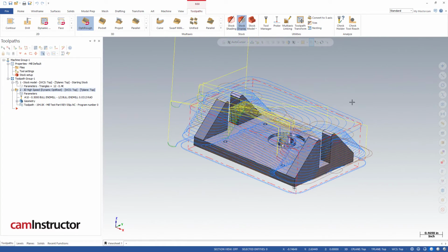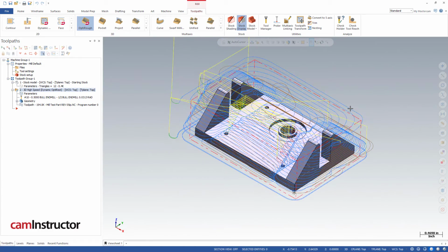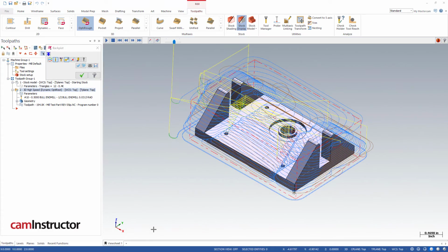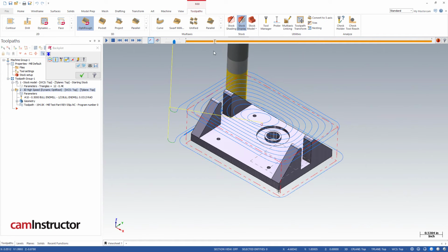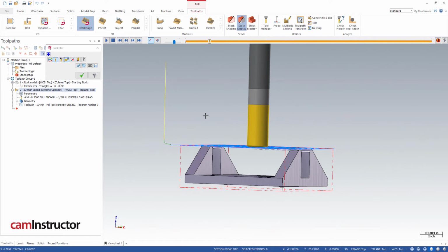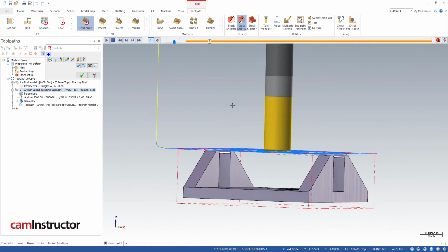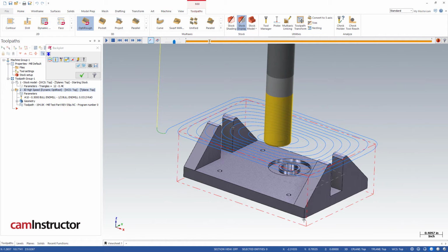And here's our toolpath. At first glance, I think it looks fine. The part's getting roughed out. Let's launch into a back plot, and we'll start dragging through this toolpath. So this right there, I don't think I'm a fan of that. Why am I not a fan of that? Okay, so remember what we told this toolpath. We said we wanted to do a step down of 900 thou and then start stepping up.